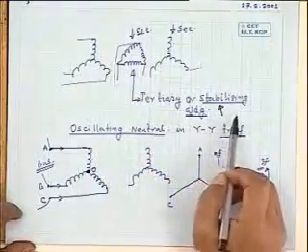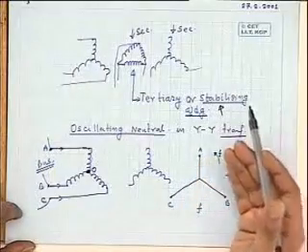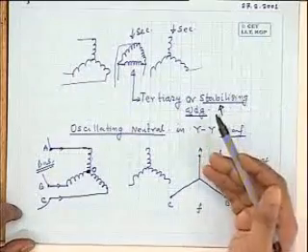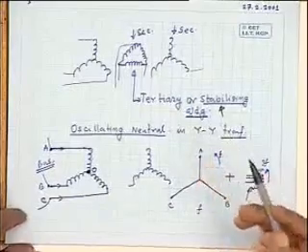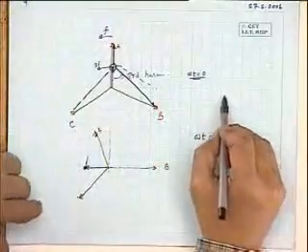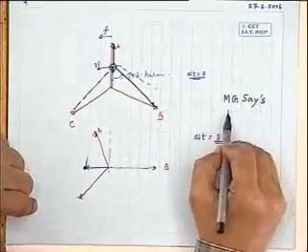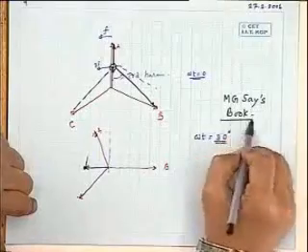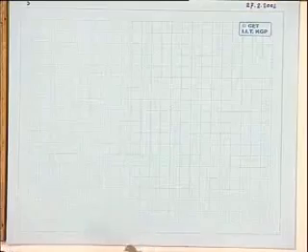So a delta connected winding can be provided extra, which is sometimes called a stabilizing winding or a tertiary winding, to suppress the third harmonic flux, hence to avoid the third harmonic voltage in the line. Anyway, you just go through M.G. Say's book once again to know further. Now, what I would like to tell is that a delta connected transformer therefore will be a better choice.